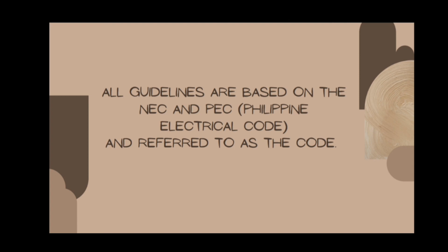15. The general purpose branch circuit should be rated at 20 ampere circuit, wired with a 12 American wire gauge being the minimum size of conductor wire required for all convenience outlets. And last one, provide at least one receptacle in the bathroom and one outside the house. Both must be ground fault circuit interrupter, GFCI, type.